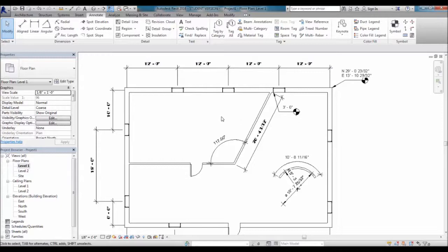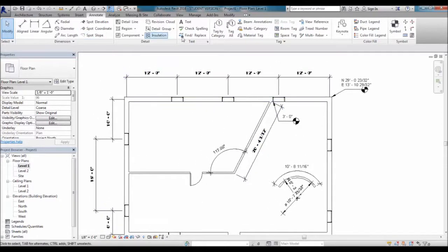One thing to note as well, with any of the 2D details that we draw here, in the text that we're printing, whether it's the dimension lines or 2D text that we place here: if you're familiar with AutoCAD, or most other CAD programs, you have what's called your model space, which is where you draw your lines and things, and then you have your paper space. Your paper space is usually a space representing the size of your sheet, and you drop all your views on there, size them and put them on there to scale. There are certain things that live in paper space and certain things that live in model space.